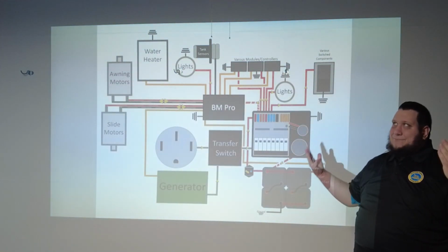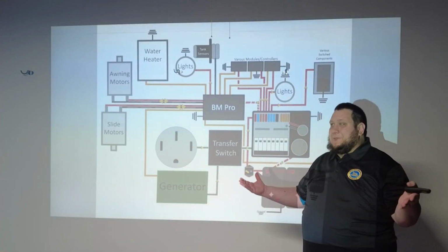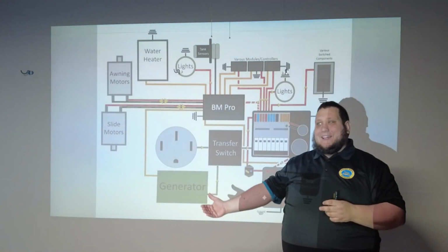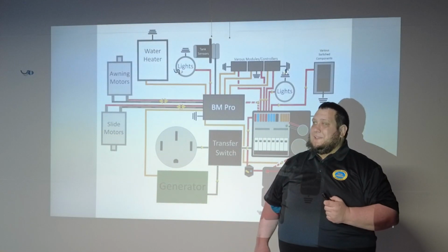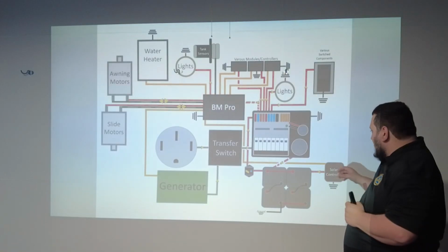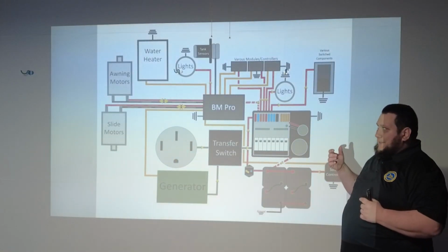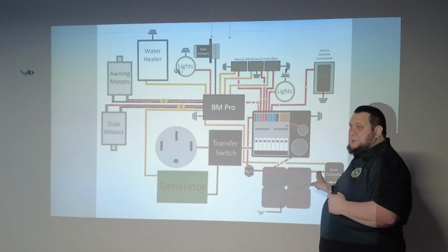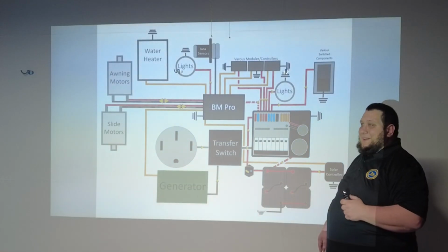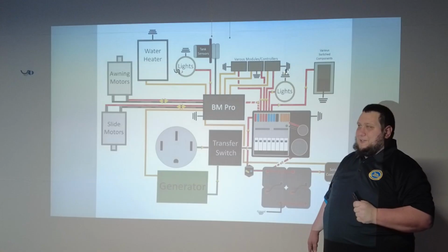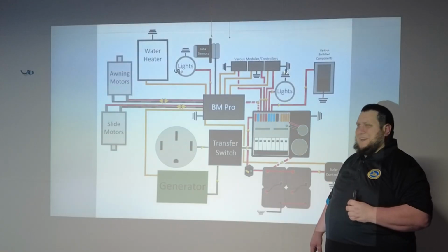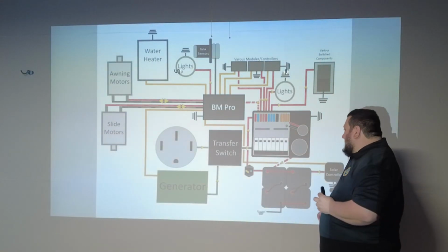So we've got, let's say, a 400 watt solar panel up on the roof. In a perfect world, let's say we're in northern Indiana, beautiful sunny day, we've got about 4 to 6 hours of usable sunlight providing power to that. I did the rough back of the napkin calculation. It's something like 13% of a full charge that you'll get in that amount of time with that kind of solar panel setup. About 13% of a charge. Do you think the customer is going to use 13% of their battery in that time too? Oh, definitely. So it might be enough.